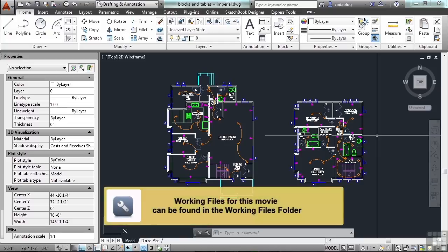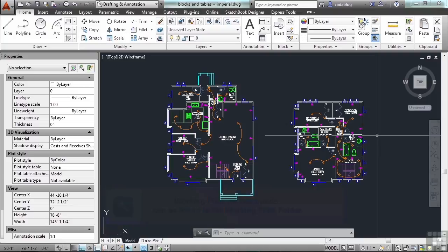One of the keys to working with AutoCAD is efficient editing techniques. One way to quickly modify an object is through grips and grip editing. You can drag grips to perform any stretch, move, rotate, scale, mirror, or various other types of operations. Grips are small, solid-filled squares colored blue that are displayed at strategic points on an object that you've selected.